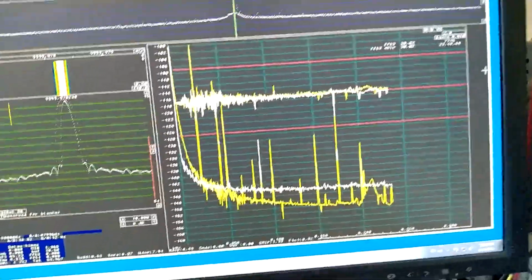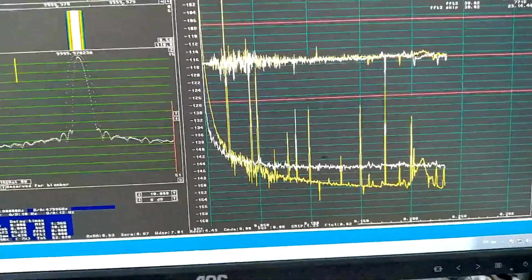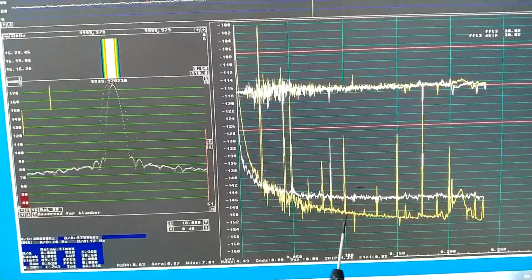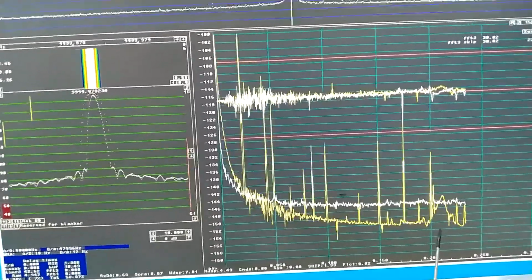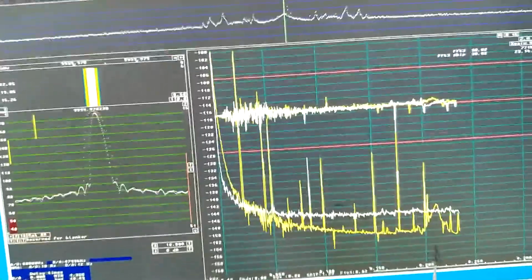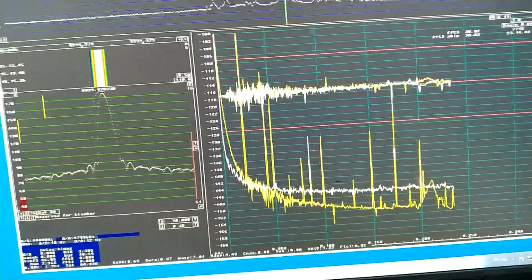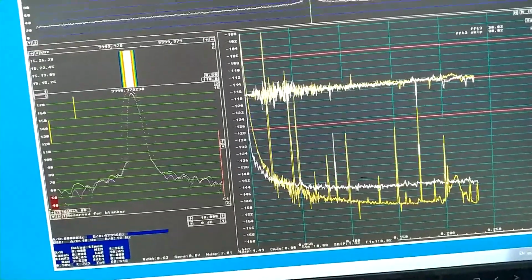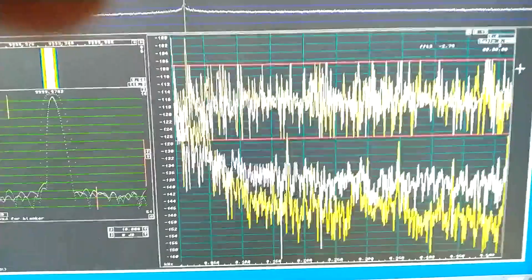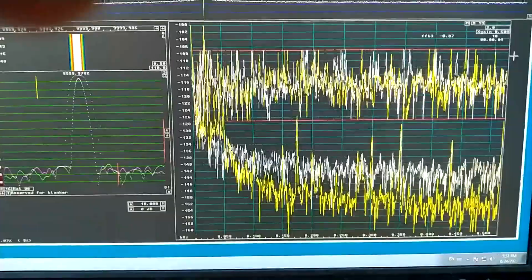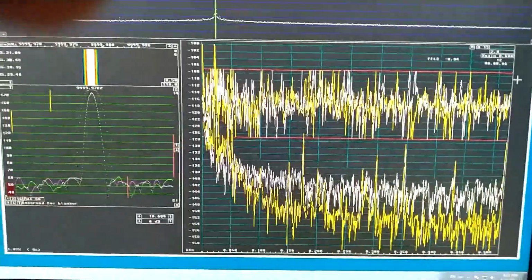But nevertheless, the values I can read now at 100 Hz minus 150, 200 Hz minus 152 or maybe 53. That's significantly better than what I had directly on the board. I have changed the parameters to get the result up to 500 Hz more rapidly.